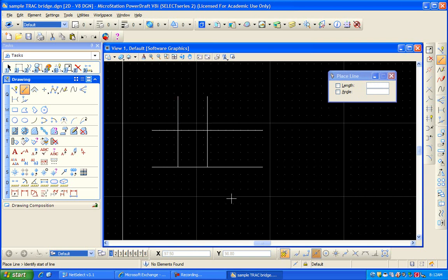So to make sure I grab those points, I want to make sure I have the right snap selected. In this instance, the snap to the end, I want key point snap. So when I press that button, it's placing that X right on the end of that line. So now I'm truly at the end there.